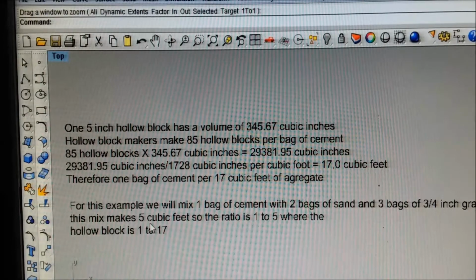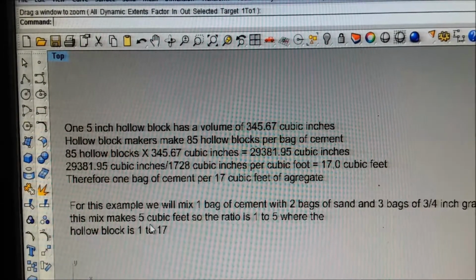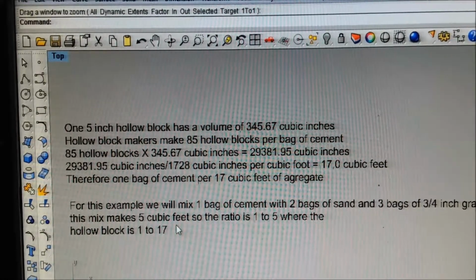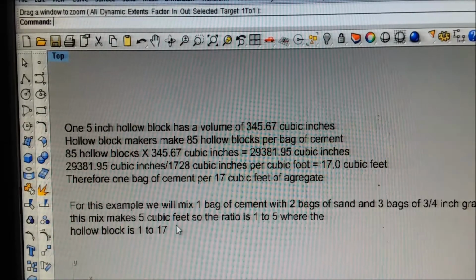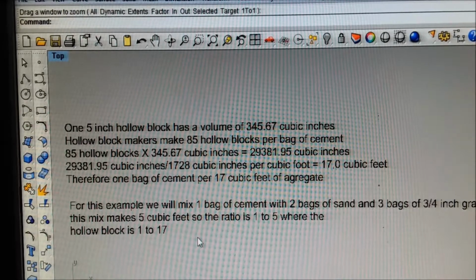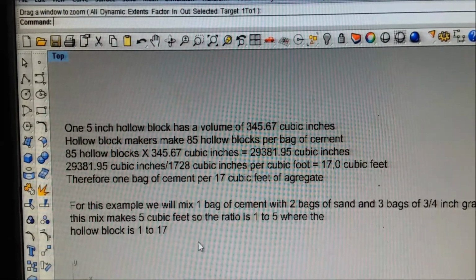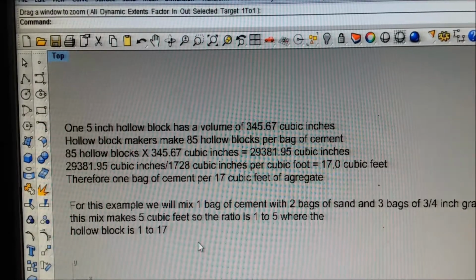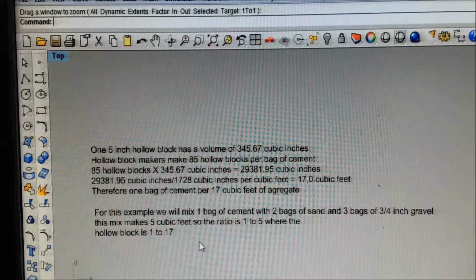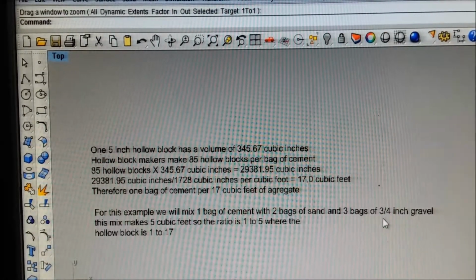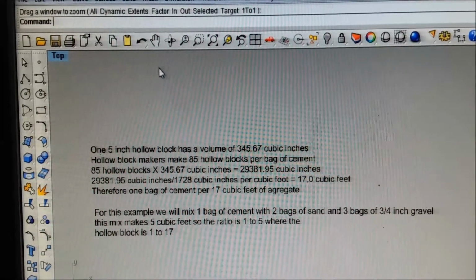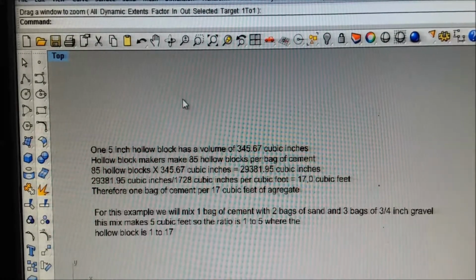If it was sprayed down with water and kept wet, and we didn't have such a windy site, this would make 8,500 psi concrete. We don't know what it makes. We haven't got test facilities. We know that we have a lot of wind, and that we can't get anybody to water it down, and don't want to have an argument about anything. We're trying to be as stress-free as we can, and there's no use trying to tell somebody that what they've done all their life is wrong. We also use very good gravel. It's that black obsidian kind of gravel, so it's probably pretty high up on the strength. But we haven't done any slump test. We poured kind of stiff.